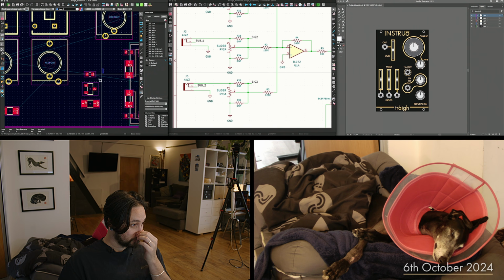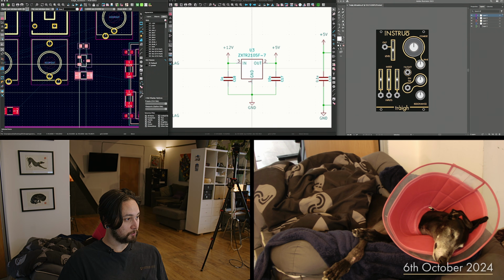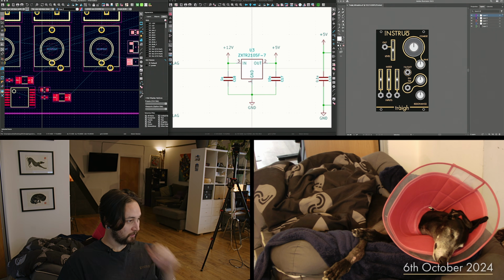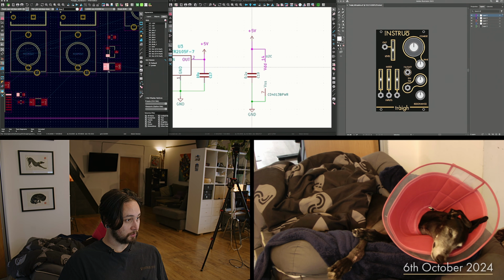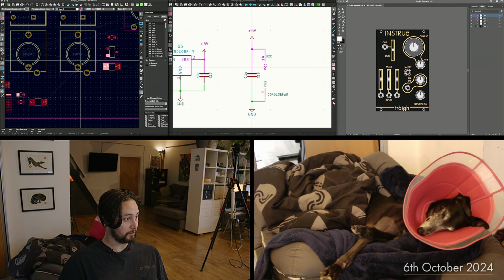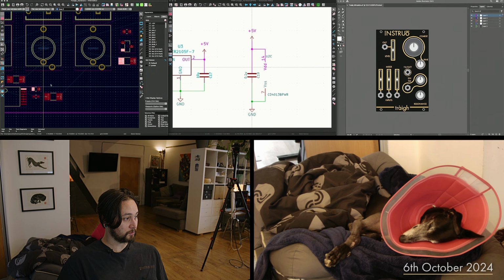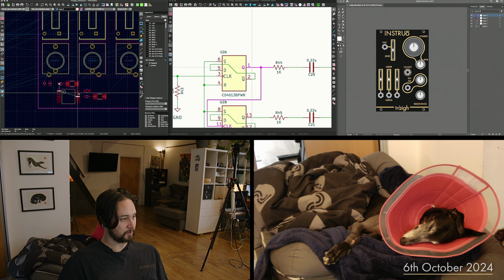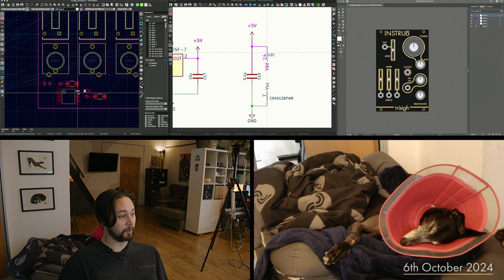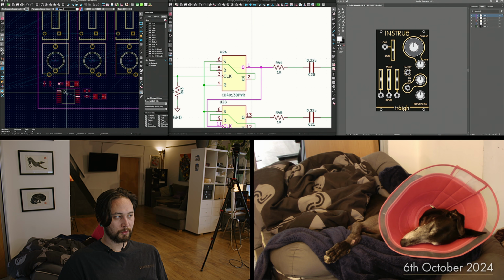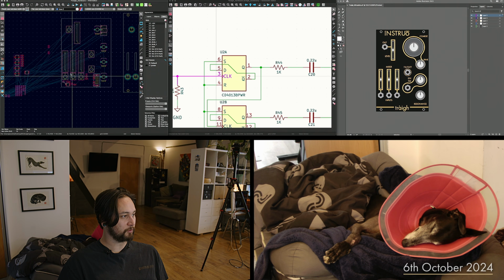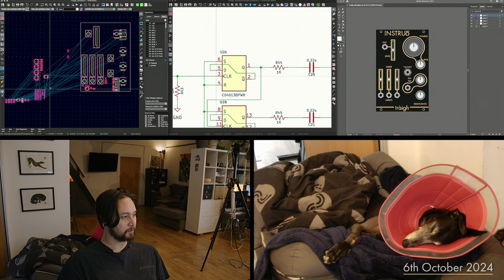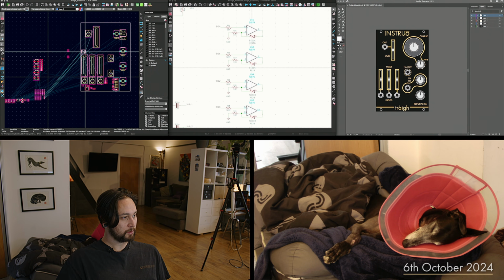So here I might actually want to move my 5 volts up a bit because 5 volts is here, so I will need to connect from here to there, so I can do that running this side. There's a kind of personal challenge, I guess: the board like this, it doesn't really matter either way, but if I can get it down to as few vias for the main circuitry as possible, that comes down to component placement, to get them as elegantly organized as I can, so that we don't have them all over the place.